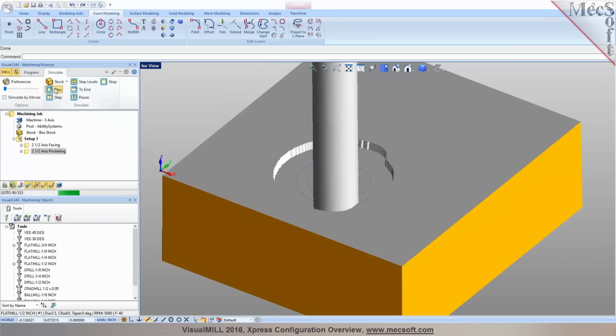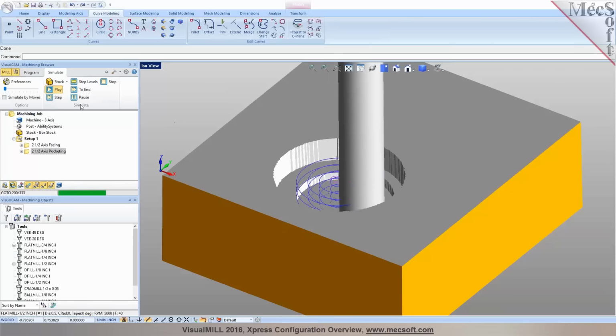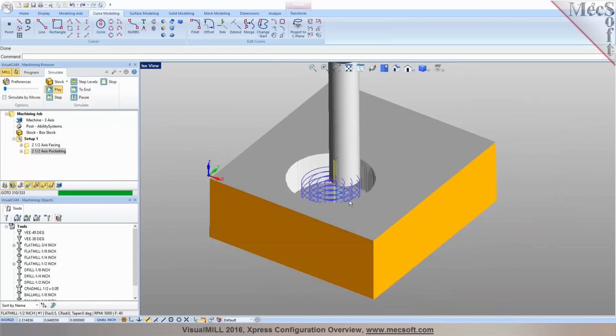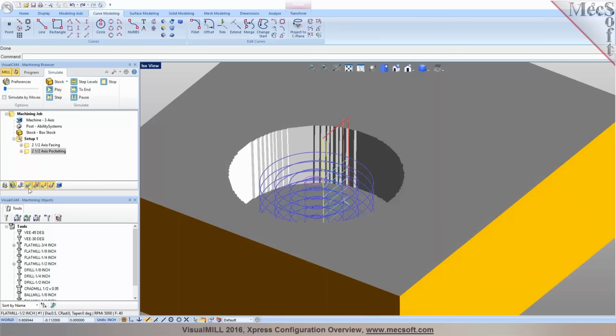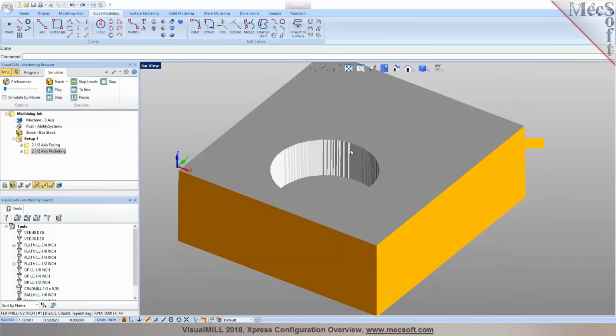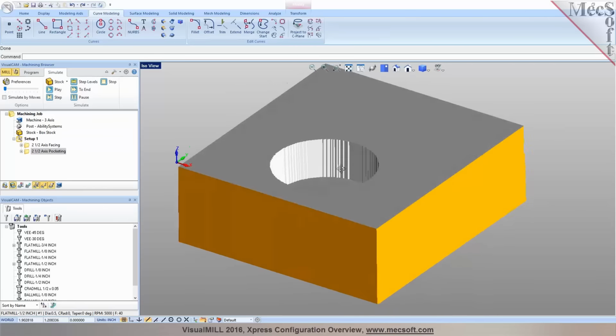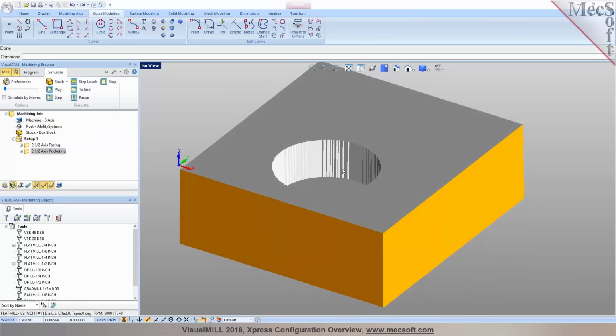And there's your cut material simulation. You could always hit the pause button and simulate to end if you'd like to run through the simulation. Now, as I pointed out earlier, the resolution is not very fine along the z-axis, you may notice these artifacts during simulation with the voxel model. If you need a much finer simulation, you could upgrade to one of the higher levels starting with the standard configuration.